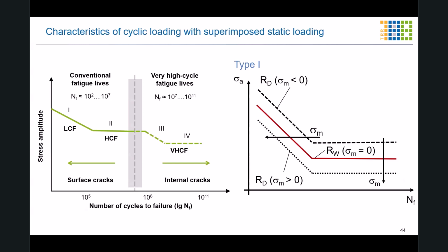In the very high cycle fatigue area, there's more importance regarding damages inside the volume, like internal cracks. For our case of the TRR, where we have the voids inside the volume, this will also be a very important topic regarding the investigation of the very high cycle fatigue damage mechanisms and the interaction with the forming-induced damage.